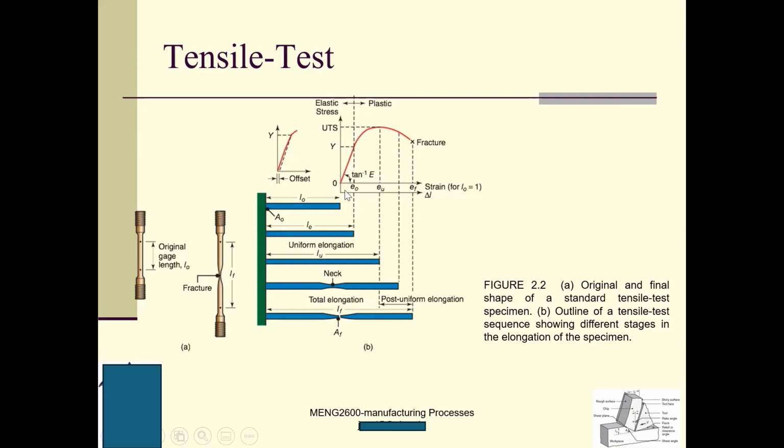Here is the strain, and here is the stress. Look at this one. Maybe you have seen this curve? Okay, if not, it does not hurt. From the origin, here is a straight line. A straight line means that for this material, the stress and strain are related proportionally. Then this Y is the yield point. After this point, the material will enter the plastic region, and so they will go this way, right?